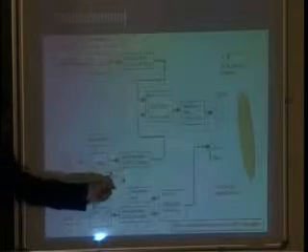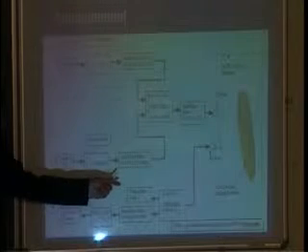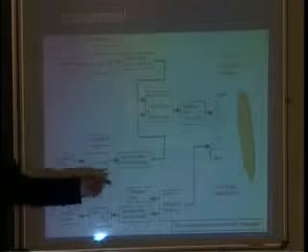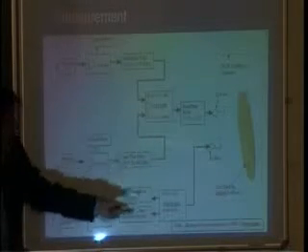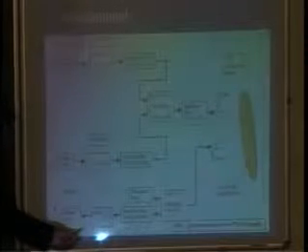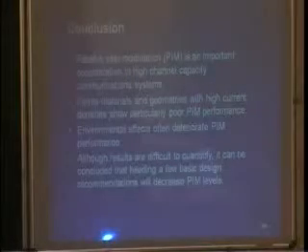Okay, so this is how you have to make the different filters. You know what type of signals you have to mix. This is one, this is the second, you mix these two and use the diplexer, and then you send a signal. And then here you are measuring after a very low noise amplifier input, because you need to measure minus 200 dBc. So for the second feed you measure the output and see whether this frequency band occurs, whether this PIM occurs or not.